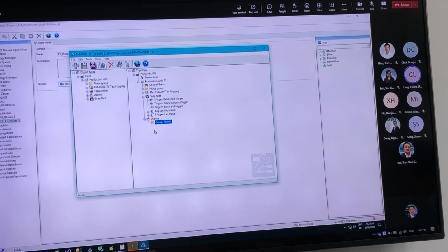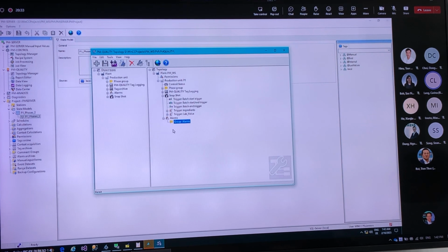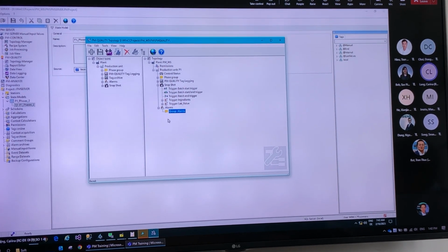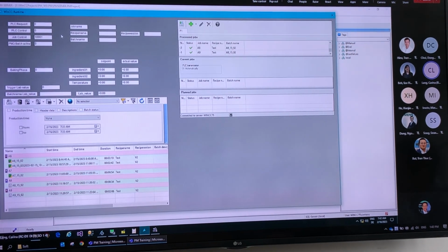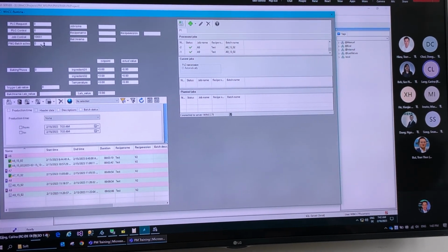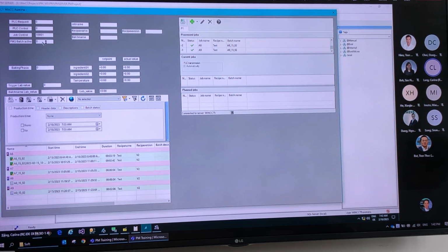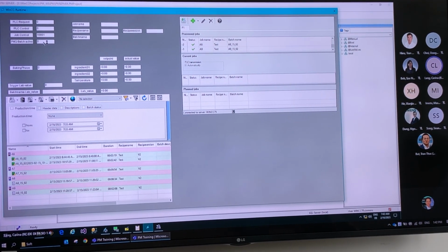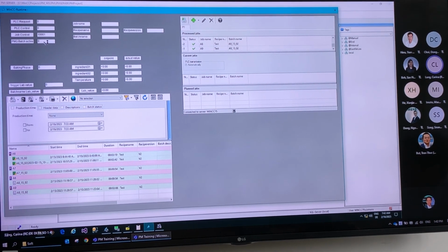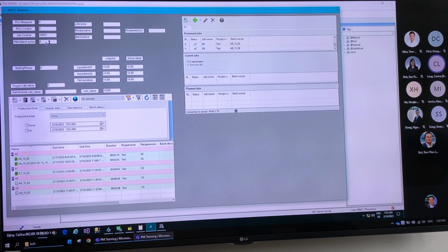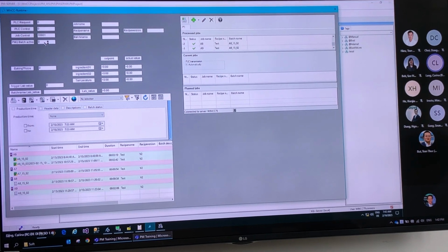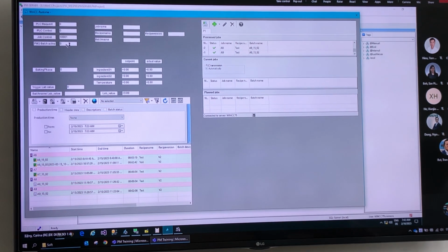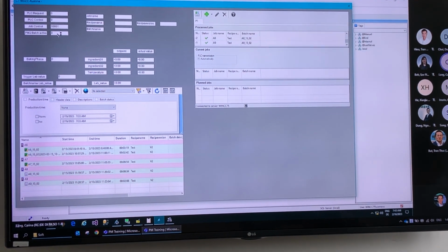Then we have started working on some batches. So we had a look at the data view. We have started a batch and stopped the batch. Starting a batch is working if we have the batch active bit, which we then just change the value from 0 to 1. That means we start a batch, and if we reset this value to 0 again, then the batch is closed. And while the batch is running, we can record all the data there.